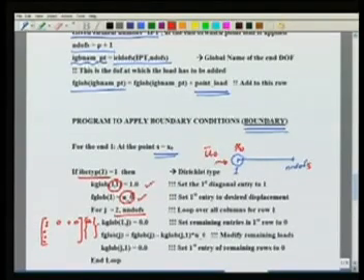So what do I do? So I go to the remaining rows. So the next row, I know the value of u1 is u0. So I simply remove this part from here. How? By first changing my f glob corresponding to that entry, that is from the second, third, fourth up to n dof, to what it was originally minus the part due to this stiffness term multiplied by u0. This is what is known. Okay. So I subtract that, and now this is my modified load entry from 2 to n dof.